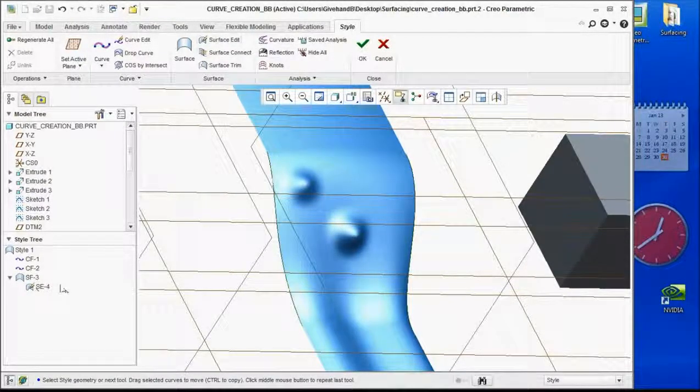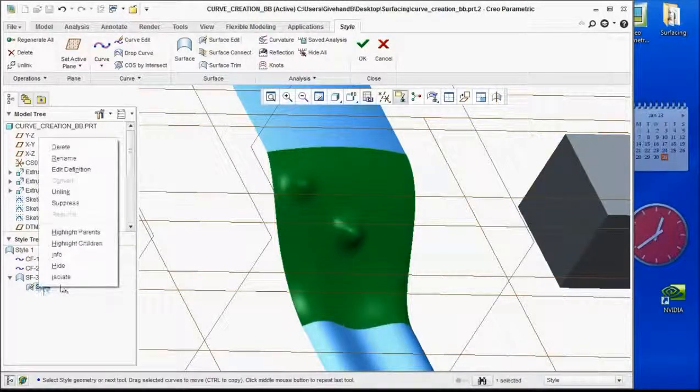And let's say we didn't like that. All I have to do is right click on this little surface edit right here and say delete, and they go bye-bye, okay? So, kind of an introduction to some of the differences and the freeform concepts within the ISDX tool and what it's capable of. So quite a bit different than what you see in the basic tools.